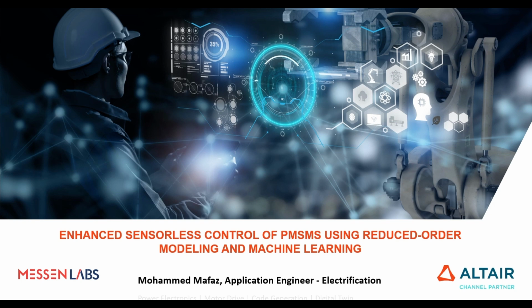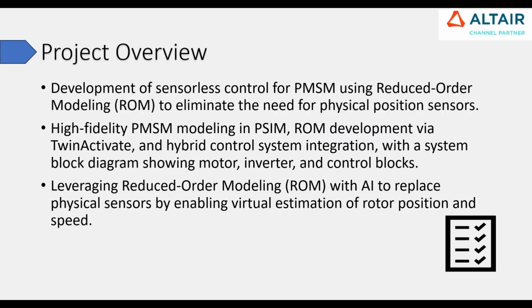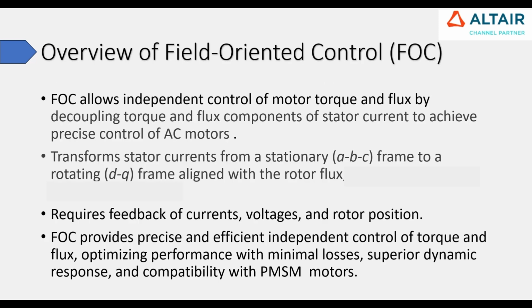Today in this problem we are developing a sensorless control for PMSM motor to eliminate the use of physical sensors. So here we see the project overview. We will be developing a high fidelity PMSM model using the PSIM software and a ROM model development using Activate. Here we will be leveraging the reduced order modeling with AI to replace physical sensors by enabling virtual estimation of rotor position and speed.